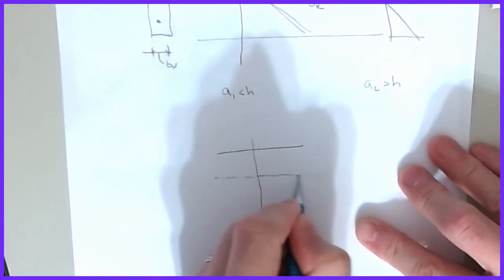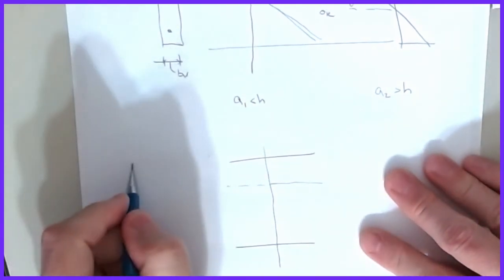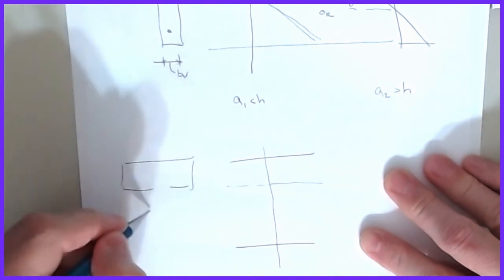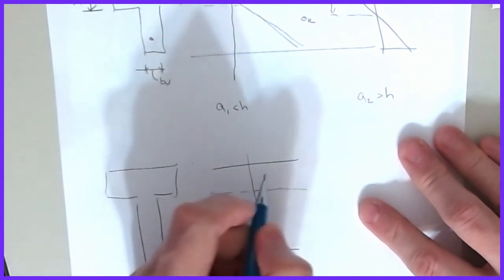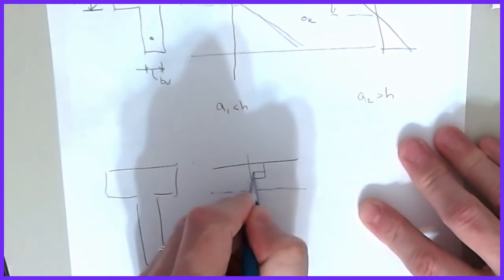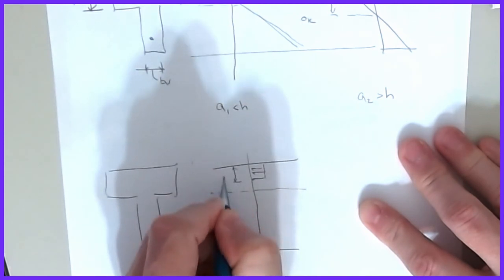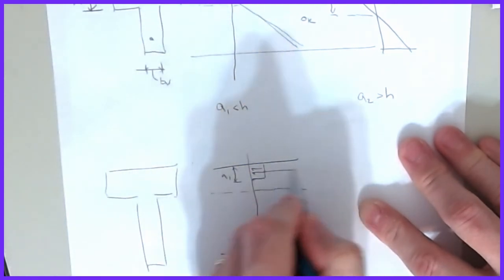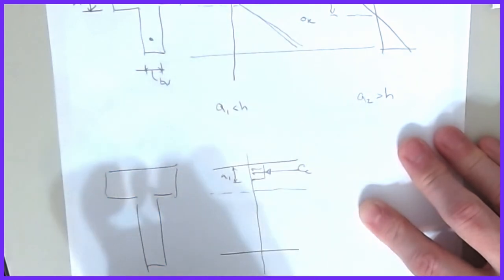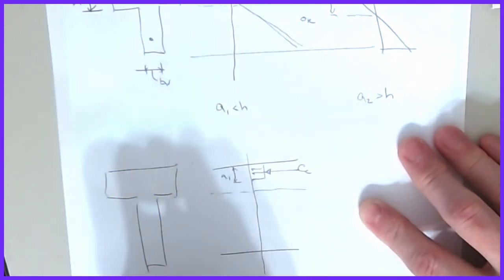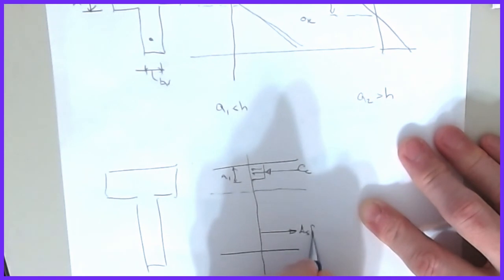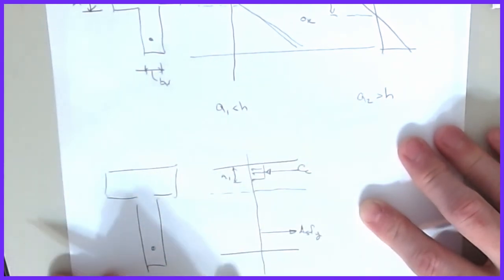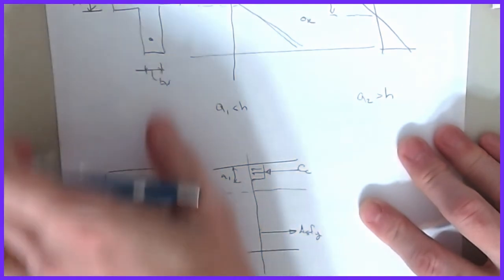So remember for the first T-beam case, then the stress block on this thing looks something kind of like this, where we call that a1. That's your compression in the slab on this. And then what happens is, remember, in concrete we neglect the tension, you're still playing the As fy game on this guy, right? So it's exactly the same way for the first case.